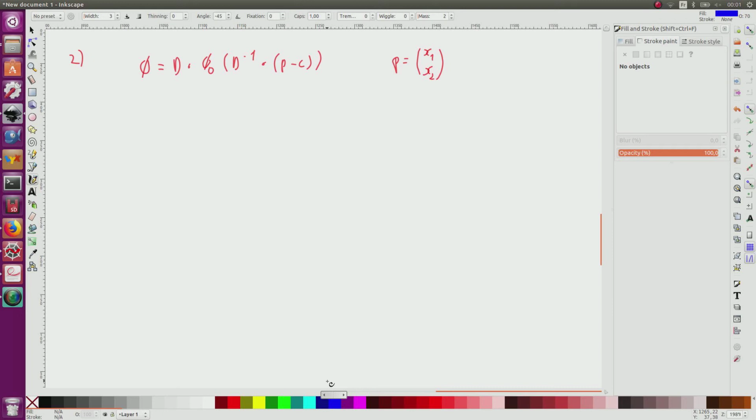So I will consider as an error, if I have my robot, which is here, with a heading corresponding to x3, and assume that phi is like this, and I want to follow phi. So I will take as an error the difference between the two angles. The error will be denoted by y, and I want it to be equal to 0, of course, which corresponds to the difference between my heading and the angle of phi.